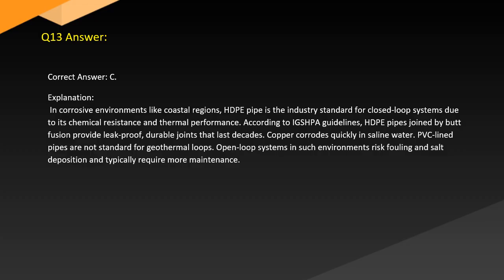Copper corrodes quickly in saline water. PVC-lined pipes are not standard for geothermal loops. Open-loop systems in such environments risk fouling and salt deposition and typically require more maintenance.